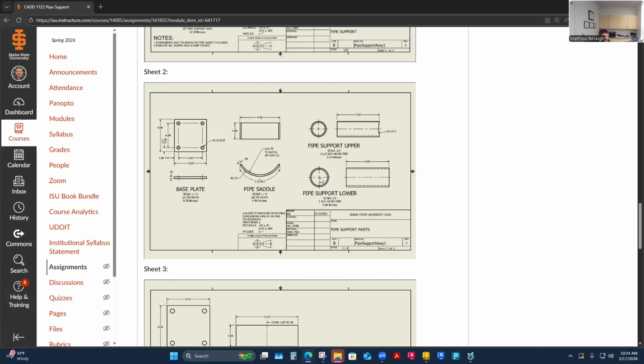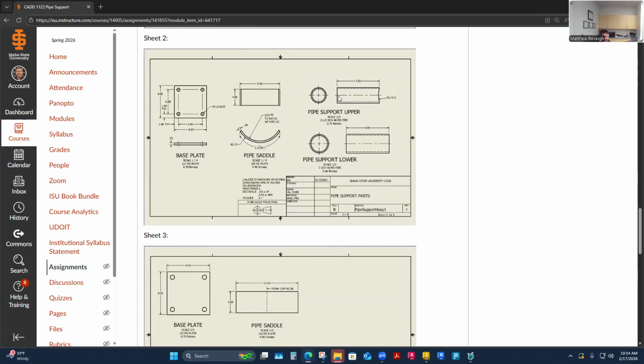Interestingly enough, you can see how simple my dimensioning is here, because really this is 2.5-inch schedule 40, so that's controlling all the dimensions. You might work somewhere where they say, go ahead and pop that dimension on there so I can see it. But for me, what's controlling that is just having that description. Maybe I'd have to go to a chart to see the sizes, like I had to do.